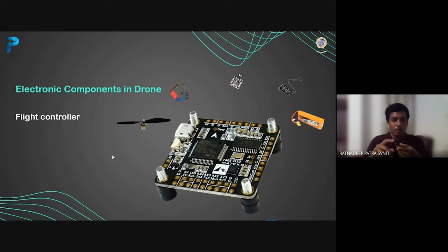So while performing this pitch action, the flight controller is constantly increasing and decreasing the speeds of the BLDCs. At the same time, it is also checking that the drone does not start to yaw, and whether the drone has achieved the pitch angle that the user is asking for. So it is checking all of these three things, in a closed loop system with the processing unit and the sensors.